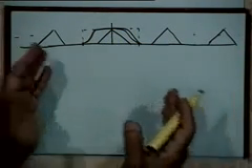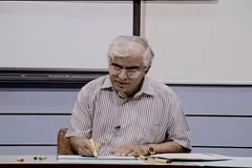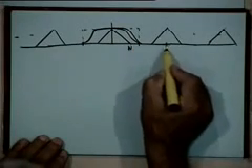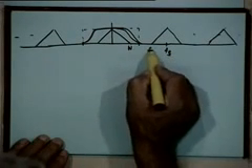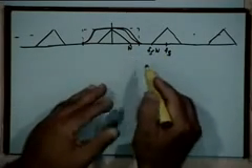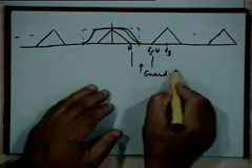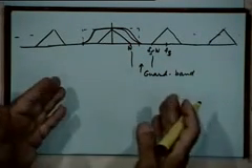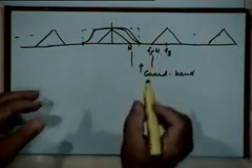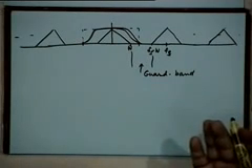Basically that is it. The difficulty in designing ideal low pass filters is typically handled by making sure that the sampling rate is somewhat larger than 2W, because this is centered at Fs. So this will be Fs minus W. You don't want this point and these two points to be close to each other. There should be a guard band. If you have a sufficient guard band, that guard band provides for designing more practical filters rather than an ideal low pass filter. That is one thing.